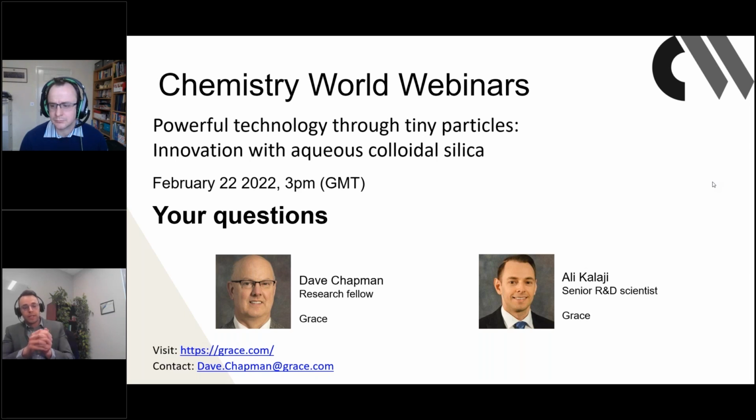Precipitated silica is actually a solid material. It is sold in a wide range of particles, mostly in the micron range, whereas colloidal silica is an aqueous dispersion of essentially nanoparticles discretely dispersed in water. And they are stabilized, as Dave mentioned, by electrostatic charge. So they are not a precipitated product, they are a dispersed solution.